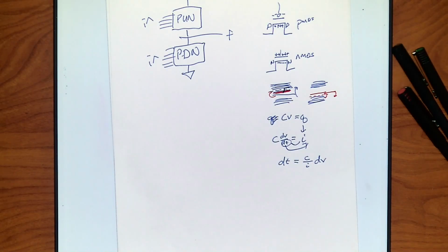I could, right? Now, are pull-up resistors fast? No. Why aren't they fast? We resist the flow through. Plus, I've got resistors and capacitors, and the second you make a resistor-capacitor system, you end up with a time constant.